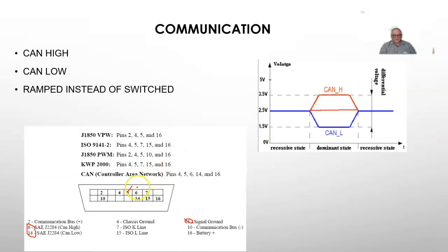Here's where you're going to find out first, is looking at your communication here, see which line went down, or both of them went down. Now you got some catastrophic going on. If there's only one computer that won't talk, you're looking at that computer problem, not the rest of the network problem. There are classes that they will offer that go through CAN communication. I think for the most part, those classes aren't that critical, because if I have a CAN problem or a communication problem, here's where I'm going to start.